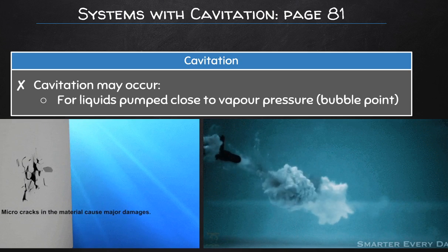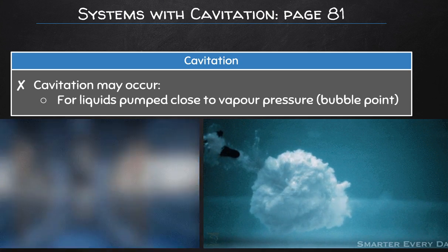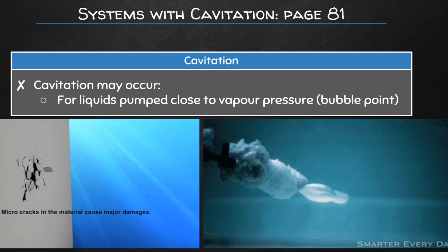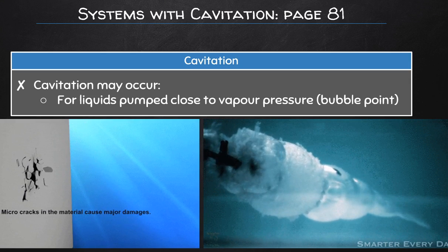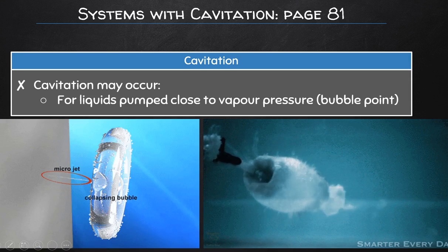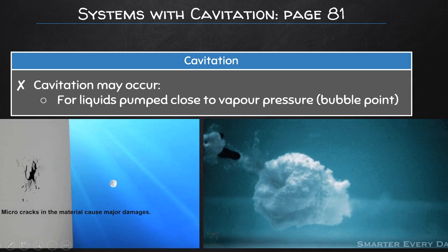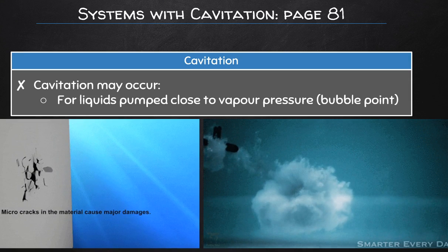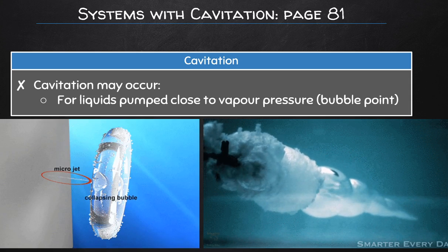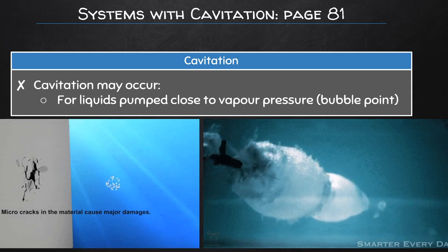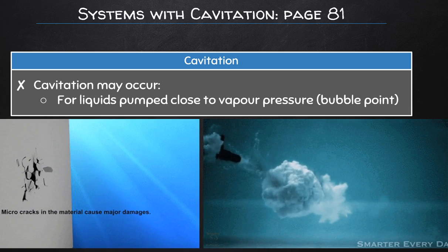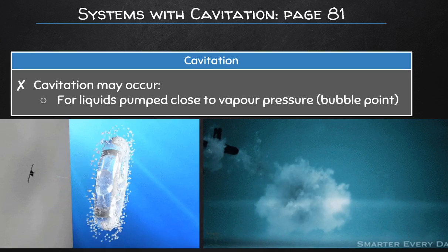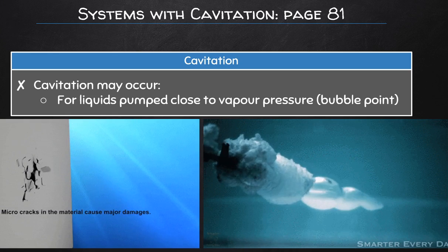Cavitation is reminiscent of vaporization. It is more or less the same thing, where a liquid that is close to its bubble point can vaporize within the fluid mover itself, or even in the suction pipe just before the fluid mover. Cavitation causes much erosion to the mechanics of the pumps as well as the pipes, and mechanical failure in fluid movers can be induced due to the sudden changes of the fluid properties, such as density.